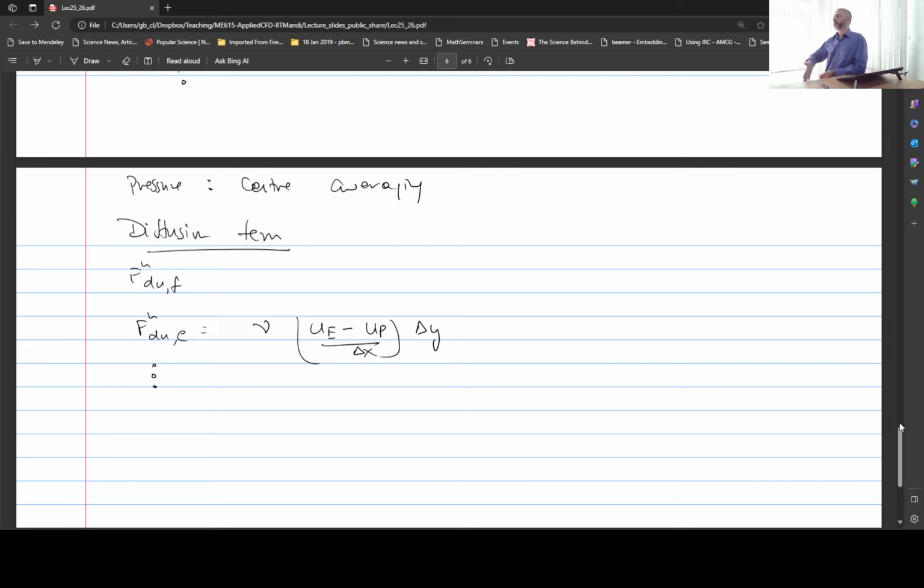And since we need things on the surface, we have to use some sort of interpolation or averaging to find that, because the variables are available only on the nodal points. So we use either upwinding, center average, or some other kinds of averages that are available. When you study finite volume in greater detail, there are plenty of things. In fact, the key idea of finite volume when you propose new schemes is to figure out how to give an approximation for the quantities over the faces using the nodal points. So you get lots of schemes with lots of different names in finite volume.